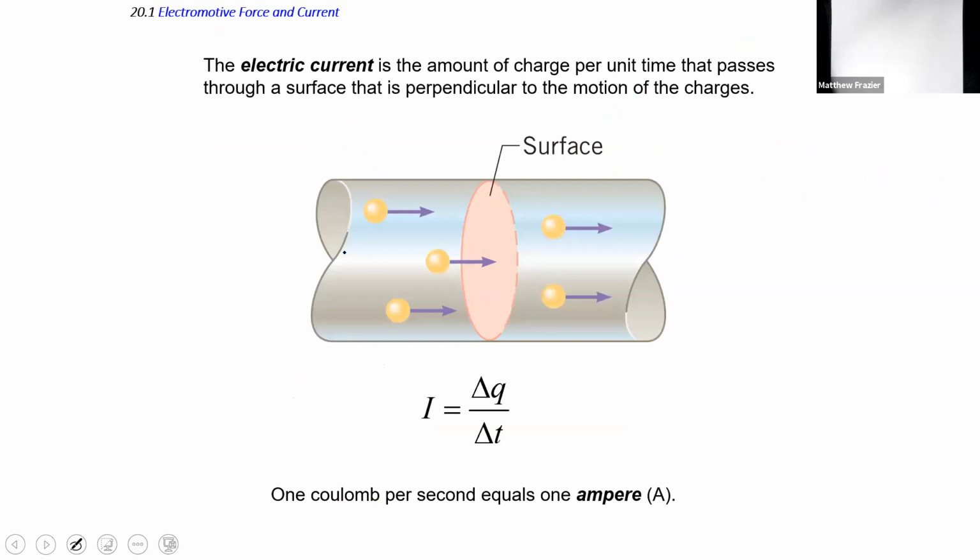So we defined voltage earlier and we did potential. Voltage for circuits is just going to be the difference in potential between two parts of the circuit. Current is going to be the flow of electrons. It's a change in charge past a point over time. Normally when we say delta Q, we mean we're taking charge away from a point. And here what we're doing is we're looking at a point and seeing how much goes by, the rate at which charge flows.